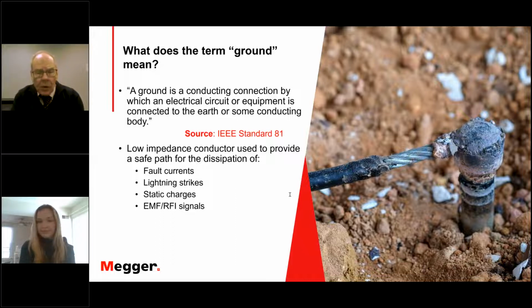the soil, so that currents that you don't want in your electrical system, mostly things like lightning strokes and fault currents from the utility and from other sources, get into the ground and out of your electrical system so they're not doing damage and not causing a hazard to personnel who happen to put their hand on something metal and get shocked. We don't want that. So that's fundamentally a ground electrode, and that's what we're going to be going back to again and again throughout this presentation.